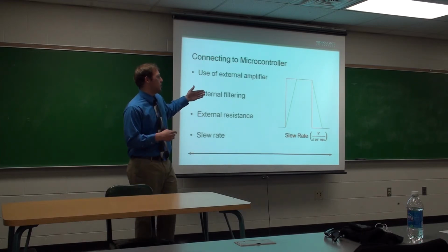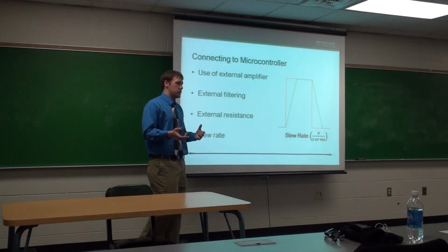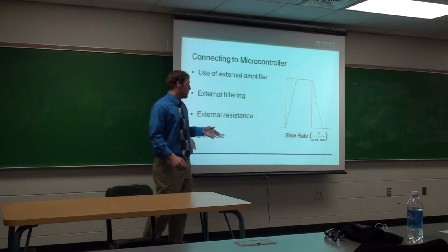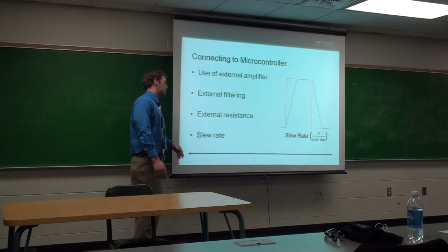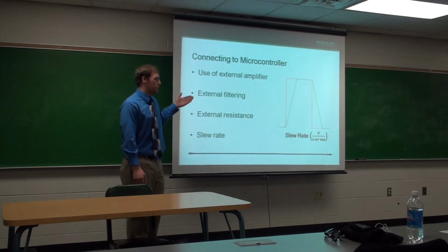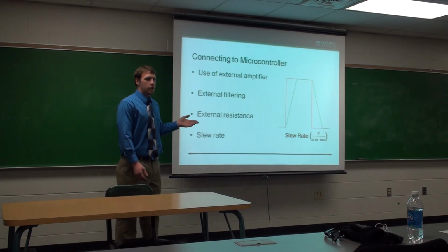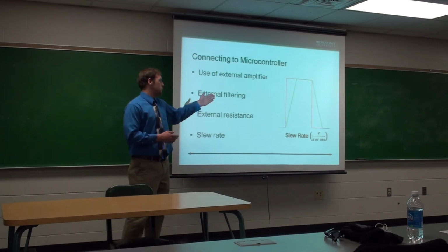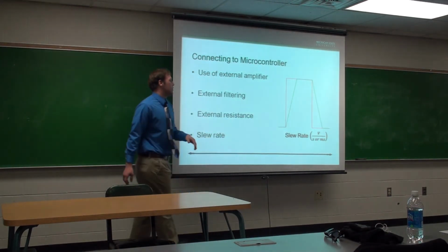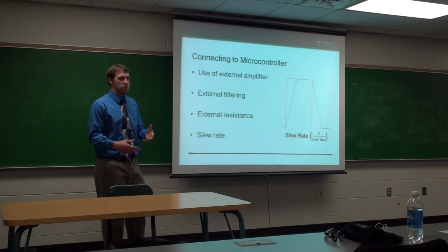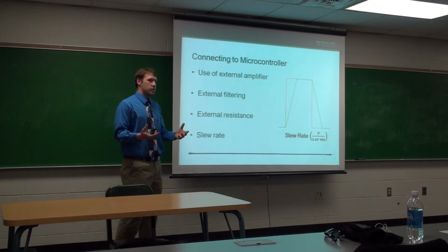the whole voltage in the circuit cannot change. It's because voltage can't change instantly all the time. You can see it's voltage over seconds or milliseconds, just depending on the type of scaling you want to use. And this can be on the order of thousands of volts to hundreds of volts. And slew rate also introduces many nonlinearities into your signal, just because of this shift we have as opposed to the reference signal here. And these nonlinearities may also introduce some noise, so you may need another external amplifier, or not amplifier, an external filter to get rid of this noise.